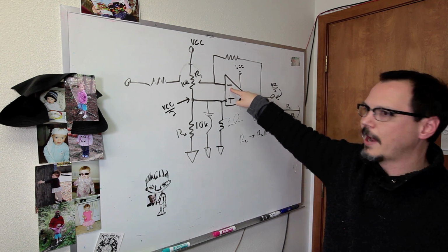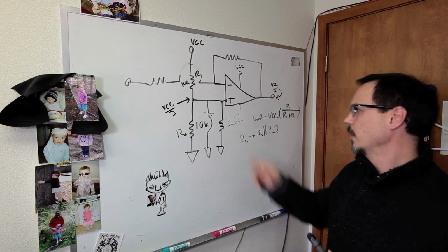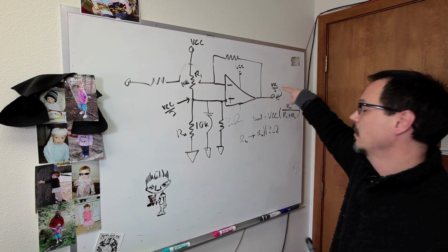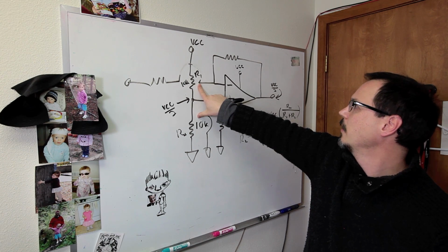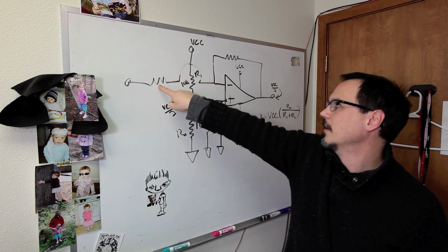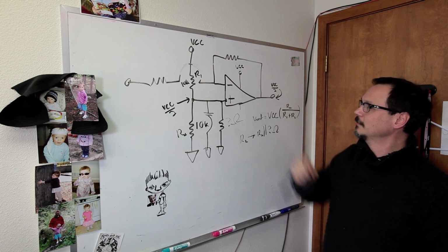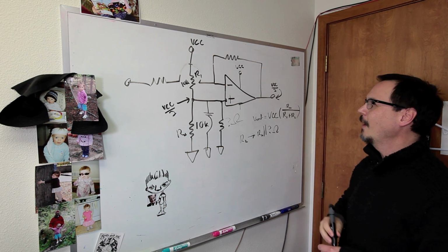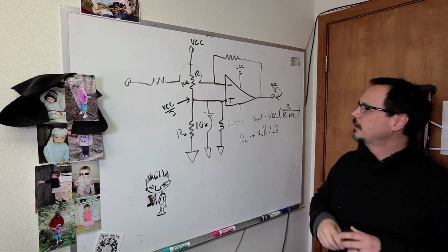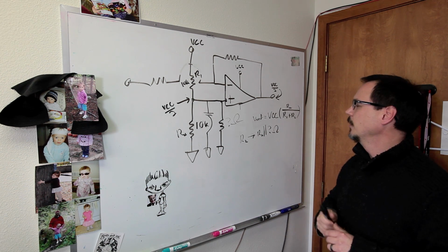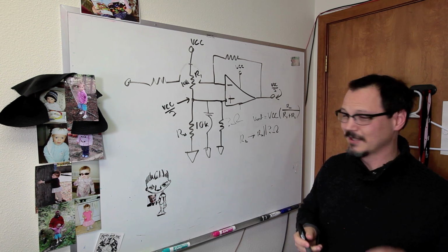The reason for that is it's supposed to minimize your input offset voltage, which can jack up your output too. So if you've got 10 megs out here and you've got a gain of 10, then that's a 10 meg, and that's 100 meg. So very, very small current. I would expect this thing to maybe get a little sensitive to noise and stuff, so you'd have to decouple this circuit at least a little bit carefully.